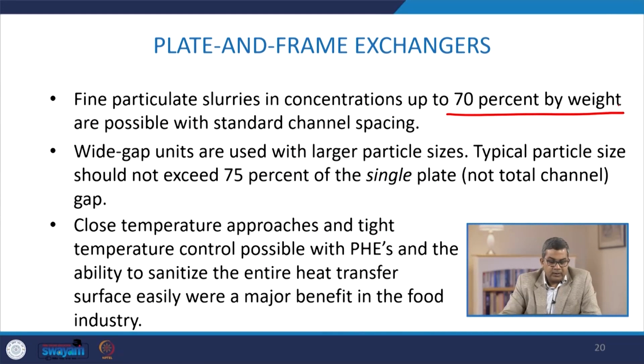Now in this, fine particle slurries in concentrations up to say 70% by weight are possible with standard channel spacing. Wide gap units are used with larger particle sizes.